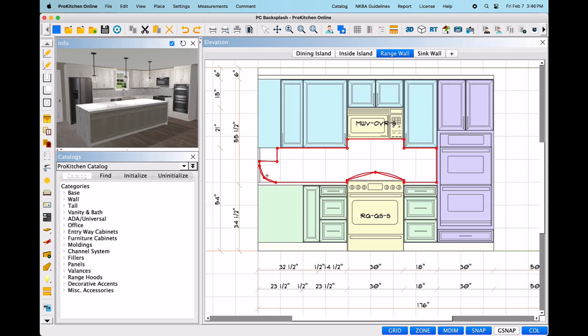Back in the additional right-click toolbox on a point, we will find Bevel. Again, once selected, you may only make this edit towards the interior of the item. This time, an angled line will appear that will essentially cut the corner off and provide a smooth straight line in its place. Once the beveled edge is in the desired location, left-click to secure. There will then be an additional 2 points and a single line in which you may select and continue creating edits.